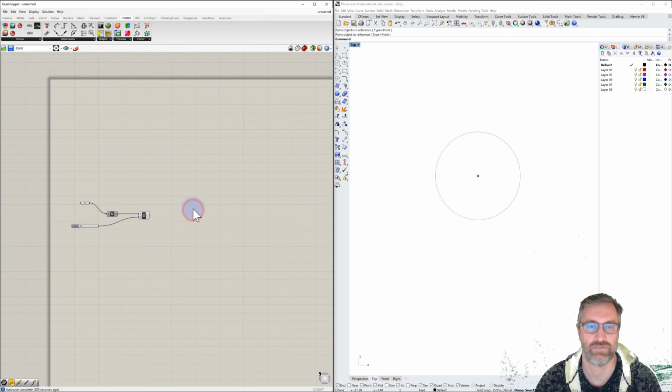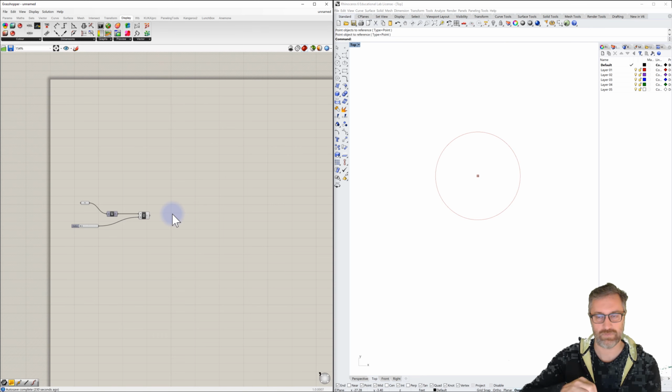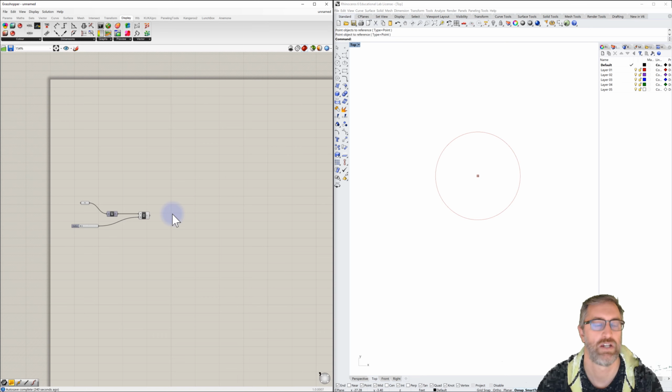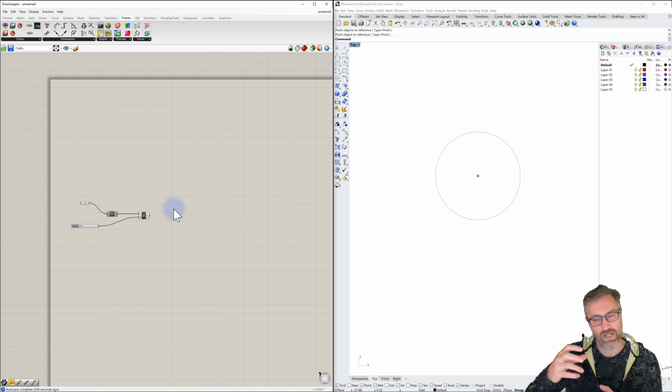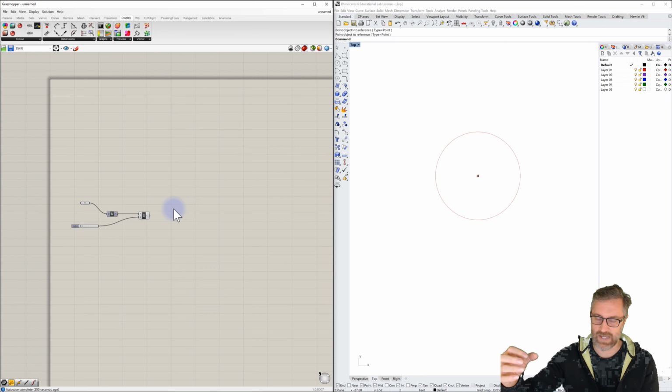So what I want to have is a line within the circle that I can rotate. Well, what we'll do first is we're going to move our center point to the vertical position, and then that'll allow us to create a line which then we can rotate. Remember, we want to think kind of procedurally and step by step. So how do I get to having that thing that I want?